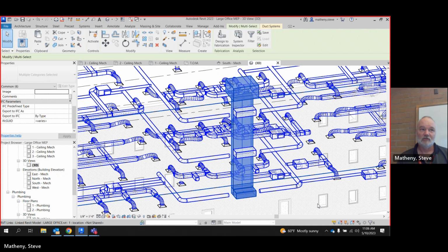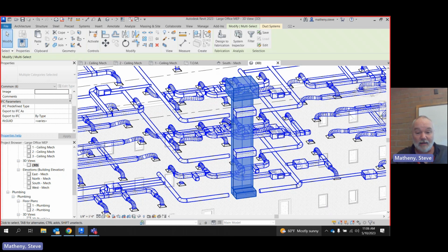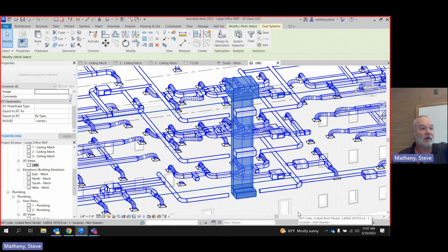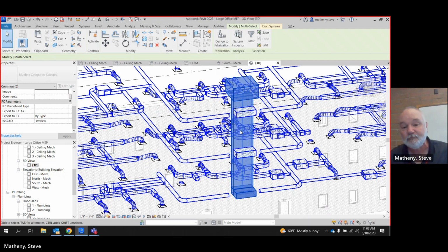Okay. So the next thing we got to do is take those 2 that we put in there. All we did was said, take this piece of duct and this cap, copy it up, copy it up. We didn't tell it to make it part of that system. Now, why is this one connected? Because when we put the plenum in and ran that duct, we ran it out. So it keeps that one part of the system because it was all put in at the same time.